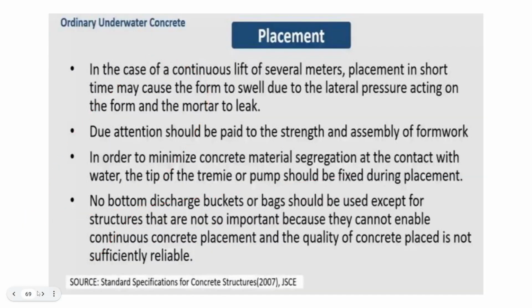So in the case of a continuous lift of several meters, placement in a short time may cause the form to swell due to the lateral pressure acting on the form and the mortar to leak. So one of the things we have to keep in mind is lifting and concreting at a very short interval. Okay, so continuous lifting of several meters in a short interval can lead to swelling and lateral pressure, which may affect the form, the concrete and the mortar. Okay, and that may lead to leakage. Okay, so due attention should be paid to the strength and assembly of formwork.